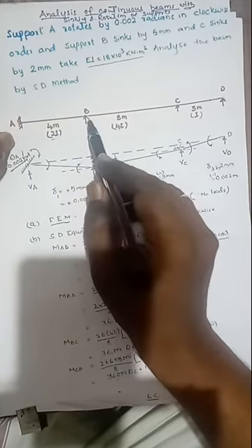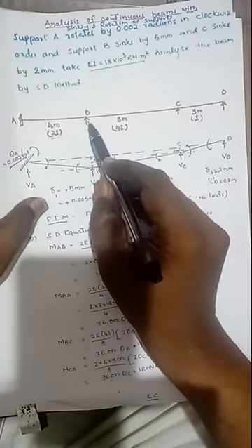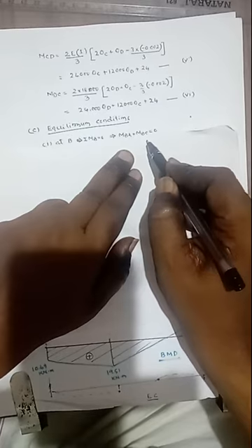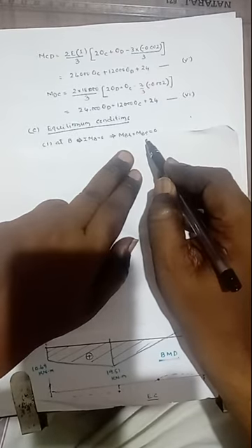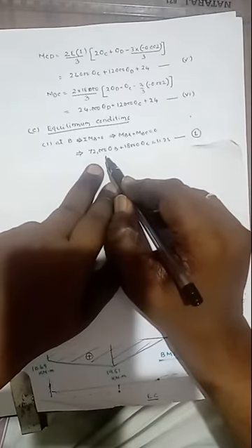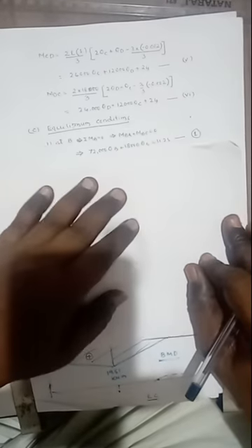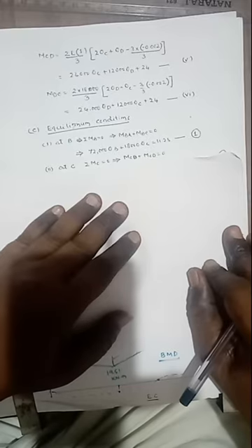Now we can apply the equilibrium condition. Here at B there are 2 members connected, one is BA, one is BC, hence the summation of the moments at this point is 0. That is, at B summation of MB equals 0, that gives us MBA plus MBC equals 0. Since there are 2 members connected at B, one is MBA, one is MBC. By adding those two, we will get, after simplification, 72,000 theta B plus 18,000 theta C, that one equals 11.25. Here we will get one simultaneous equation. Then here there are 3 unknowns, theta B, theta C, theta D. We must get 3 equations, 3 simultaneous equations.